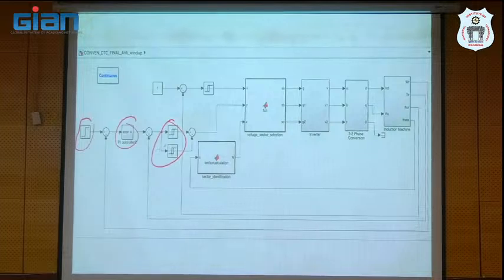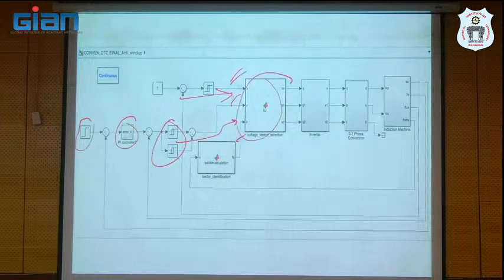If the error is crossing the limit or not, we can define. So this is for flux. Finally, this is the flux controller, this is the torque control: torque state, flux state, and sector number. By using these 3 inputs, we can generate the states of SA, SB, SC.